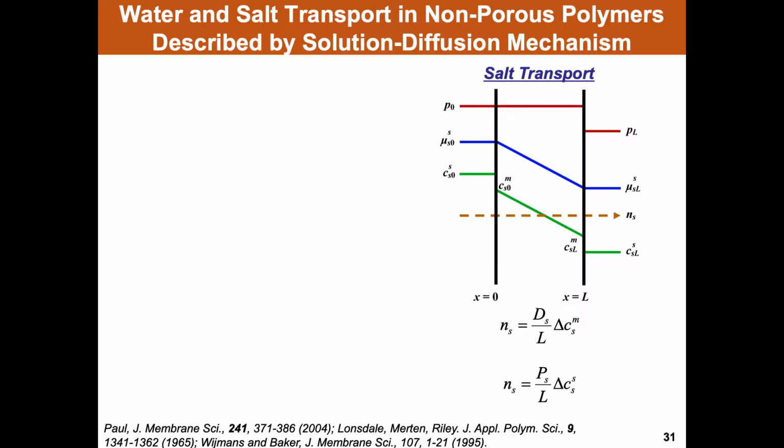I wanted to talk a little bit about water and salt transport through polymers, and today focus mainly on water transport. This is one of the most interesting technical problems and somewhat counterintuitive bits of science that we'll talk about this term. And for salt transport through a desalination membrane, which is a non-porous membrane of thickness L, the steady state salt transport is governed basically by Fick's law.